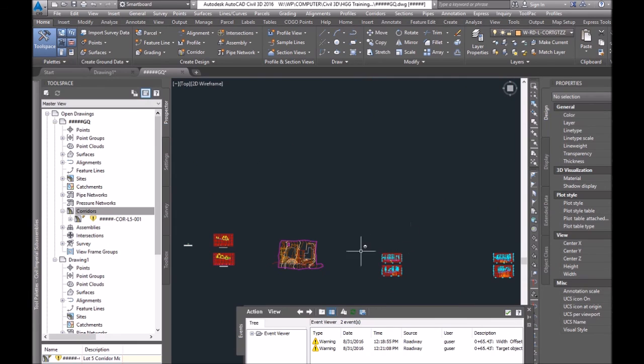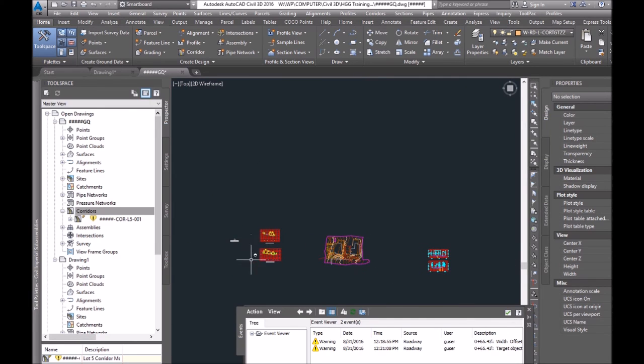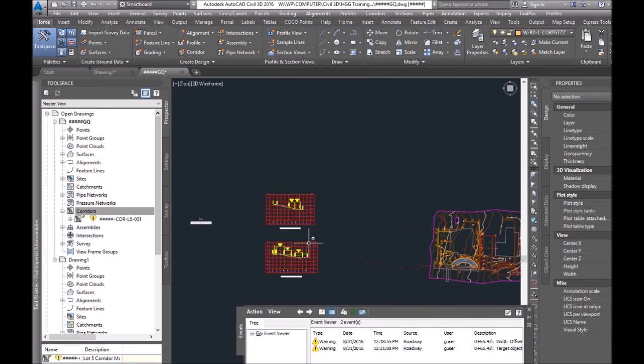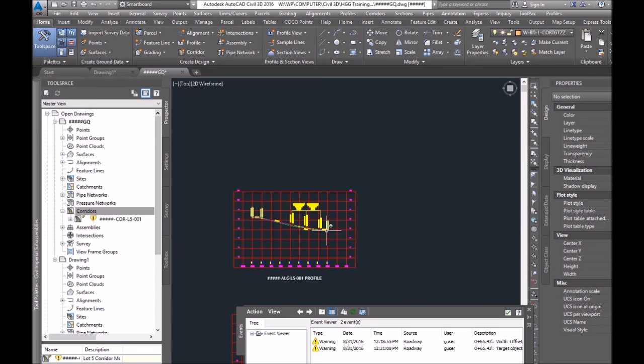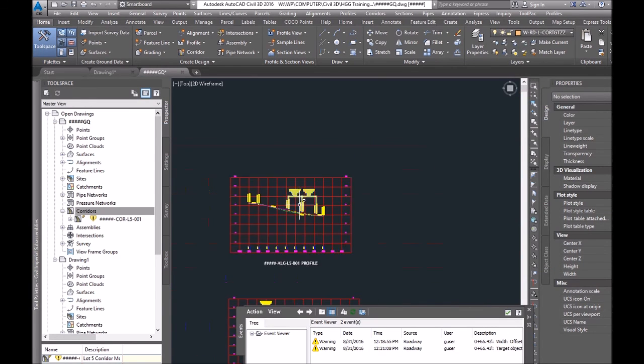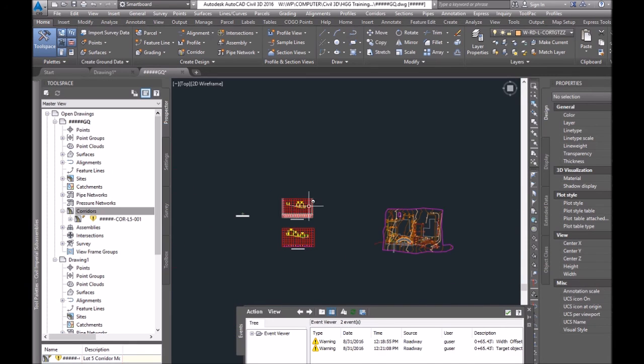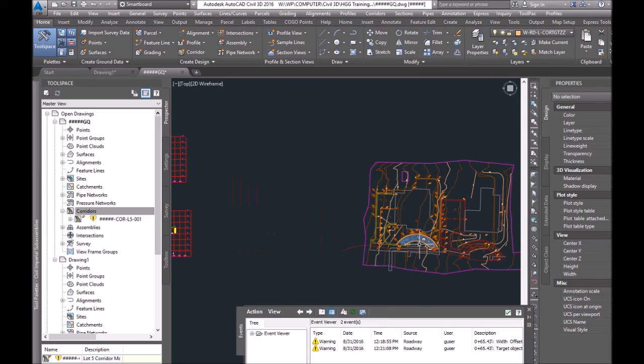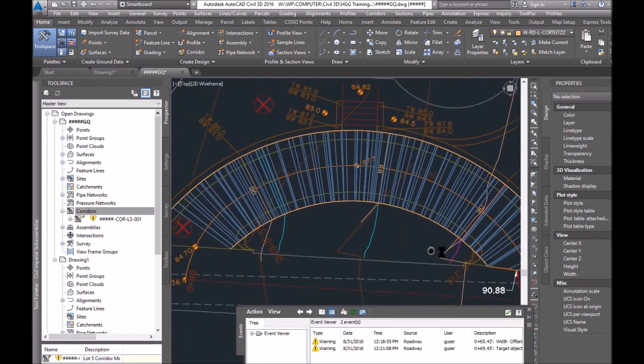All in all, creating these corridor models, you have to start with the driveway profile. And so the design starts with this road profile being right where you want it. Then your cross section, and then an idea for what you want it to look like in plan.